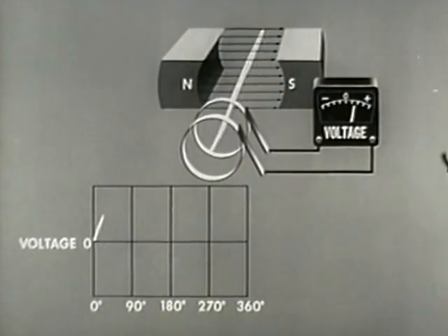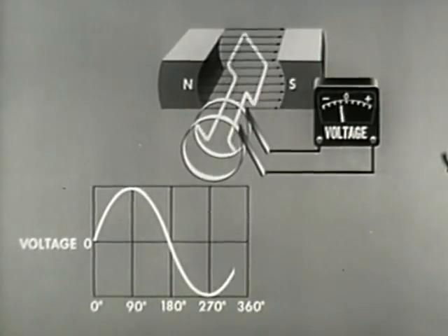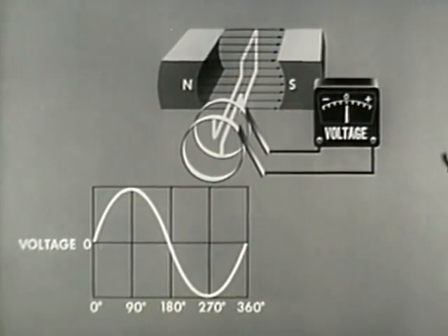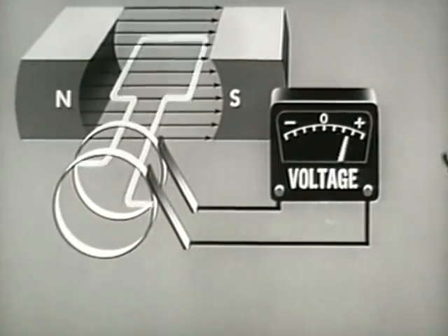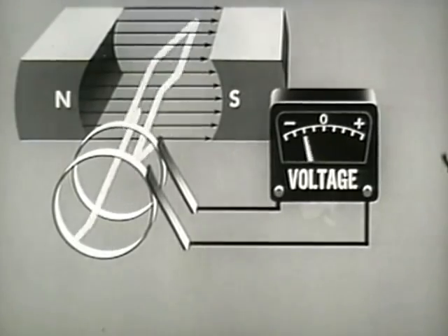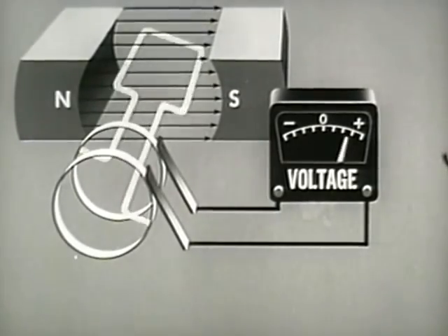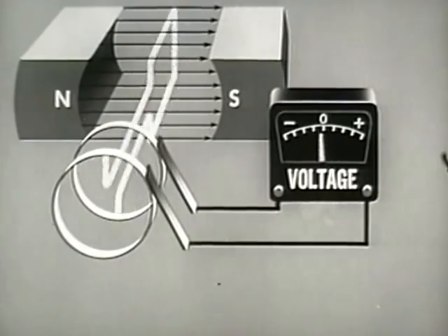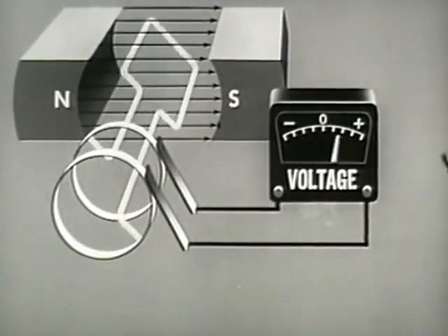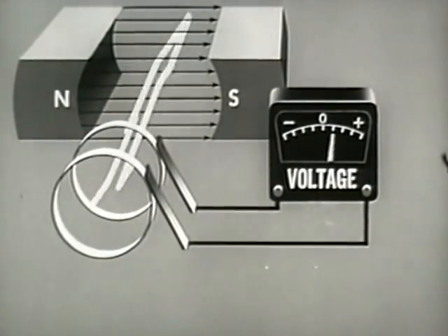This capability is responsible for the development of radio communication. All generators produce AC internally. In this basic AC generator, the arms of the loop cut lines of force in opposite directions, causing electromotive force of opposite polarity to be generated in the conductor. To maintain the AC character of the output in this generator, we use slip rings instead of the commutator segments used in the DC generator.